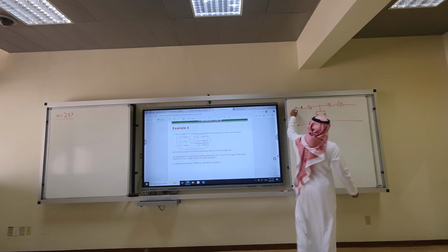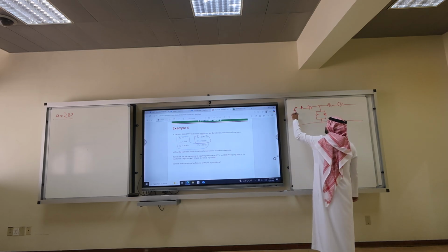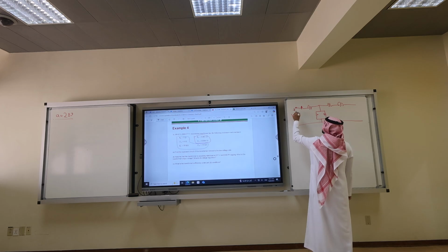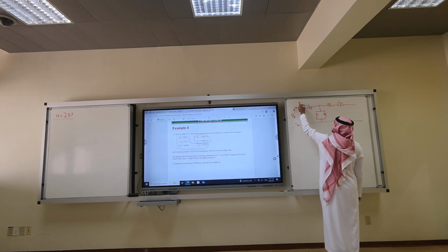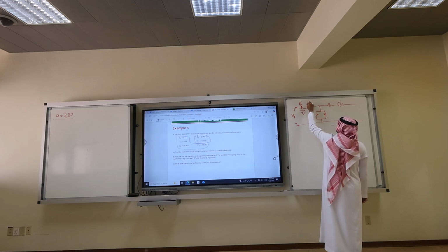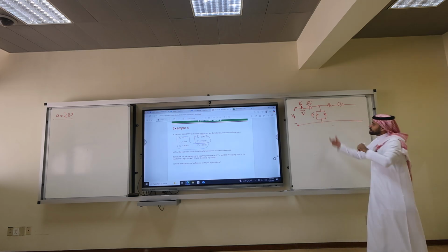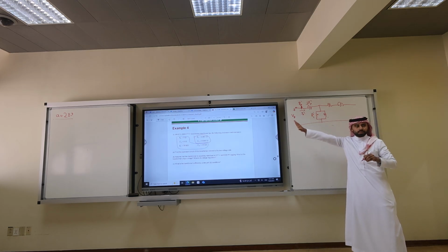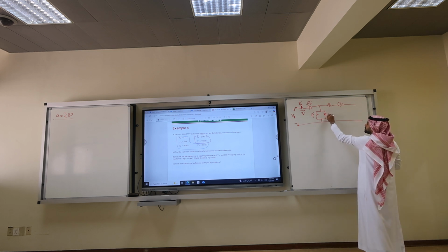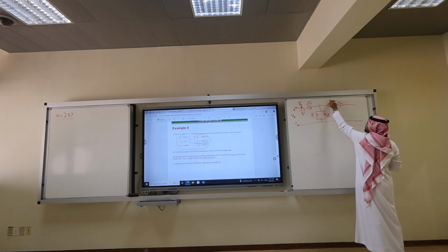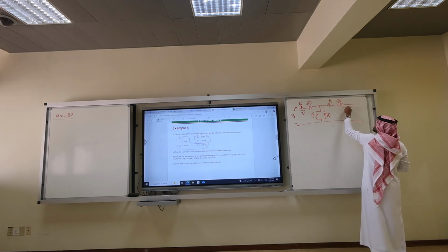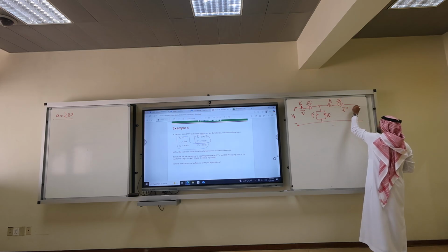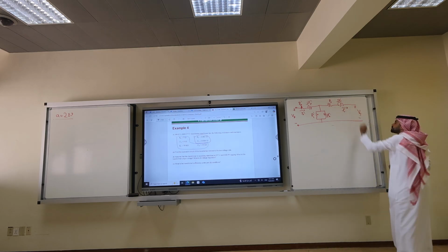So now he's asking you, what is the voltage here? VP or VP prime? What is the current here? IP prime here. RP prime here. JXP prime here. RC prime. Remember, the parallel component belongs to the primary. Here. Here. RS, no prime. Here. What is the current? IS, no prime. What is the voltage? VS, no prime. Get it?